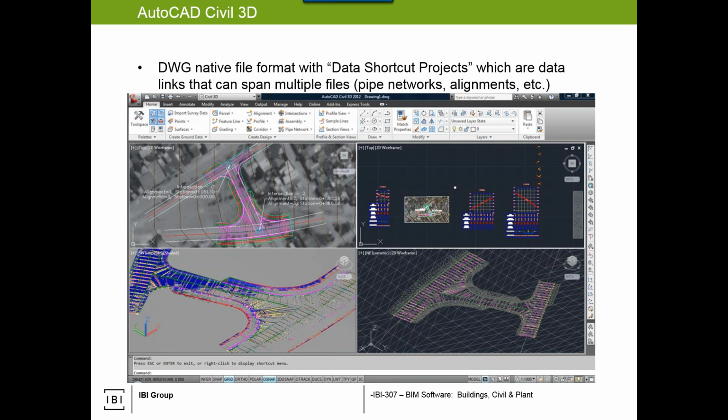Now, as I mentioned earlier, it's rare to have a BIM project where everybody's using the same application. So I'll say even in a Revit project, if you have ARC, Struct, and MEP all using Revit, there's still a site. There still has to be some interaction between that building model and the site model. Now, if the site's just being done in 2D AutoCAD, that's one thing, but if it's done using Civil 3D, then there is that question of how do I interact between Civil 3D and the coordinates and Revit and its coordinates, and how do I ensure that I'm seeing the data back and forth? We have workflows to address all of that.